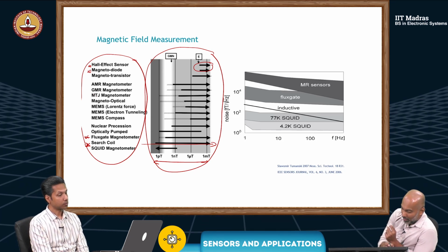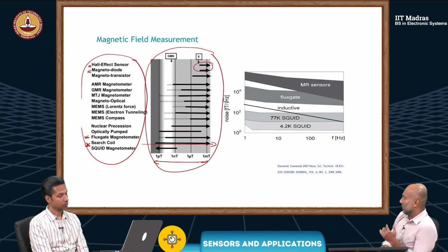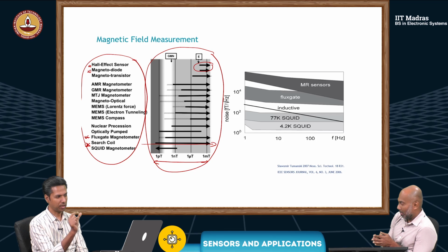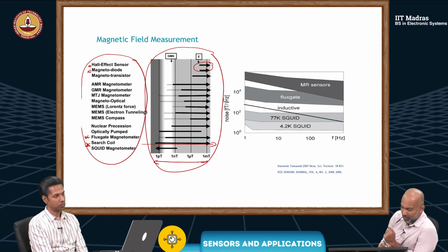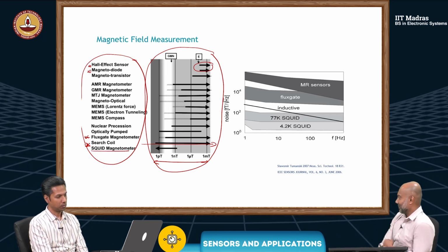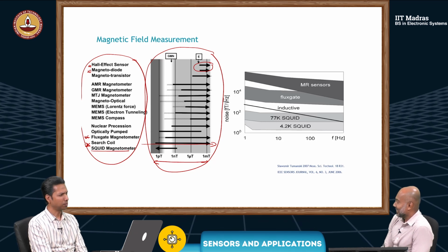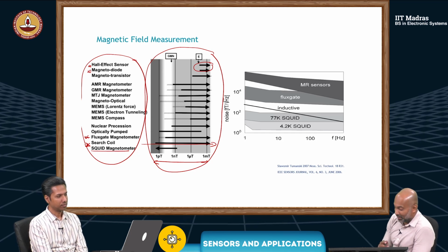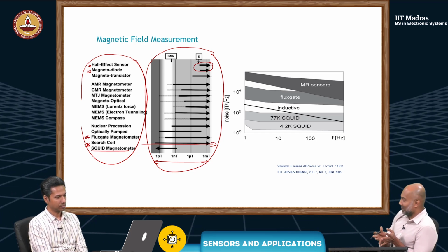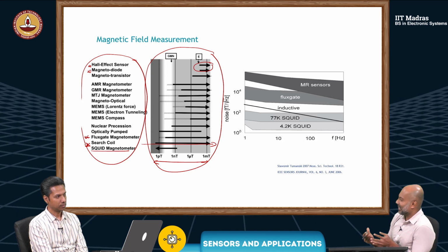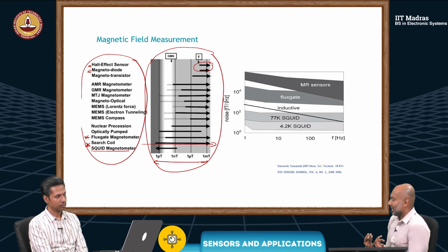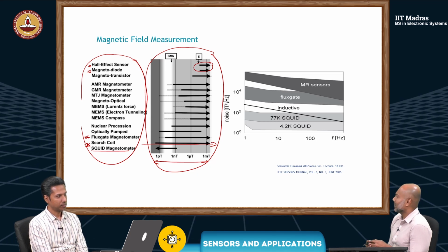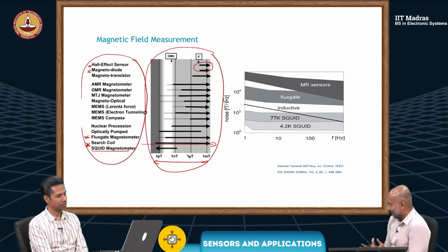Now, the magneto resistive sensors and the Hall effect sensors, you can actually make them very small. Yeah, IC form. But let's say a SQUID sensor. I heard this requires some very low temperature to operate, and is heavy. Yes. SQUID can measure very small magnetic fields, but it's limited in the sense that it requires some helium or nitrogen cooling to operate.